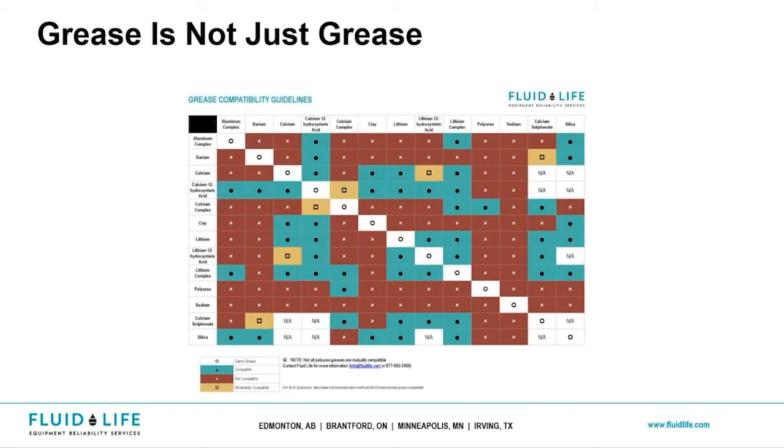So number one would be seeing what's in the thickener, right? Is it a calcium base? Is it a lithium base? Is it a urea base? Is it a sodium base? Those things matter and are extremely important so that you don't have the grease automatically rejected and you have a main bearing failure or generator bearing failure or a pitch and yaw related bearing failure, right?